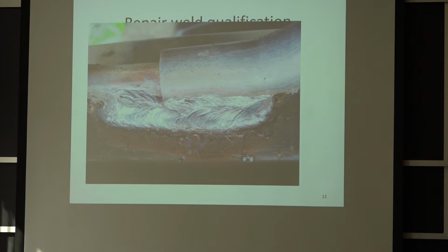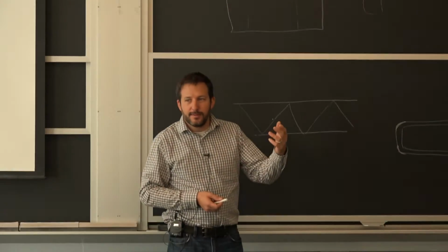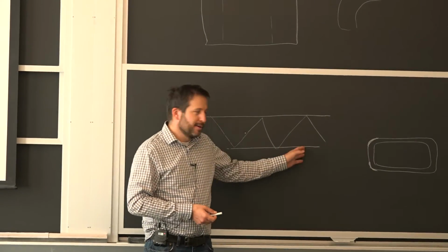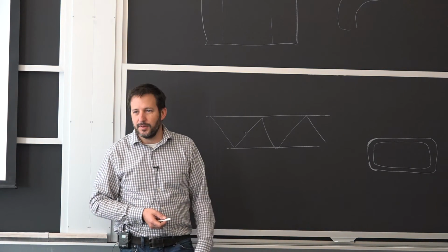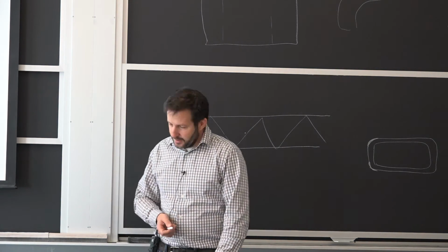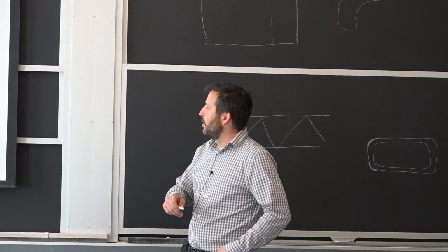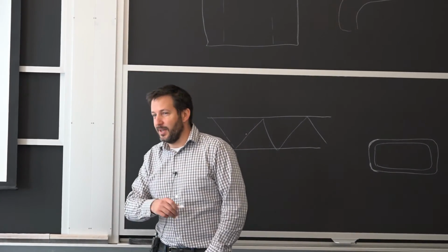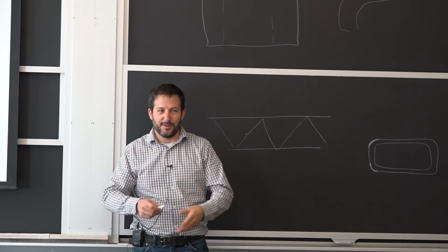But they had 2,500 joists times 40 welds per joist. So things just start adding up, and you start calculating and say, well, it's going to be the summer, and we may be halfway through it. So it was very difficult to deal with the issue other than shoring those joists. So they bought 2,000 posts, put them in the middle of each joist to take the load down by a factor of 2 or 3. And then this concept of having the welders over the tomato plant didn't get anybody excited. You have spattering and all sorts of things.